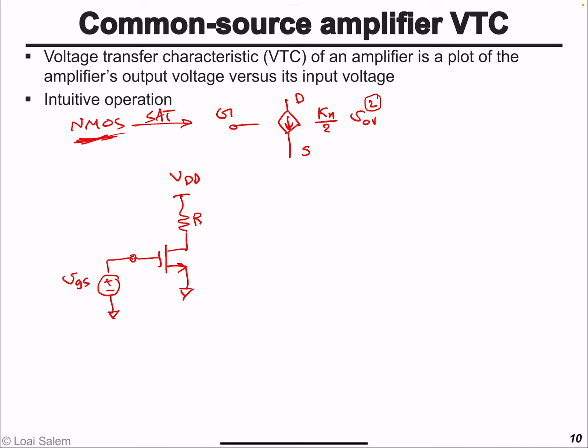Okay, so this acts as a voltage controlled current source, assuming it's in saturation region, and then this is basically the loudspeaker equivalent resistance. And VDD, as we're going to see in the future, essentially behaves as what's called AC ground. So for the AC signal that's produced, which represents a replica of the actual voice produced from the microphone, which is the useful signal that we need to amplify, essentially, we'll see the VDD supply as an AC ground, as a ground basically. Okay, but that's something we'll discuss in the future.